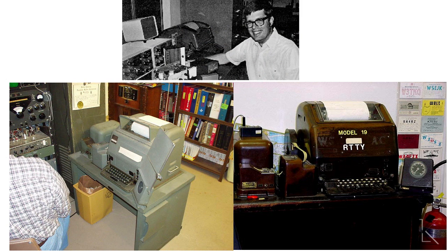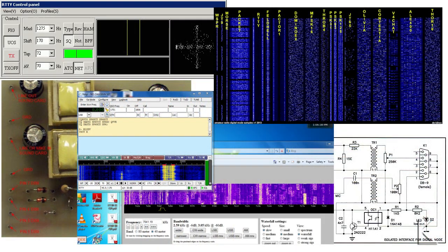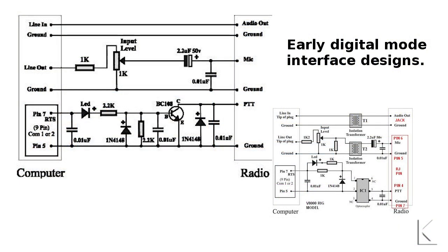In recent decades, due to computers coming with built-in sound cards, hams have invented or adopted many different ways to send text, images, and other data over the air. Today, there are approximately 30 or more audio-based modes of transmission. Early computer interfacing was done directly from the computer's built-in audio connectors to the radio's mic input and headphone jack. Push-to-talk was accomplished by using signals from the serial port and some discrete electronic circuit to key the transmitter when those serial pins went high.